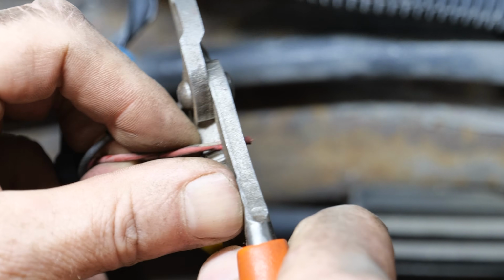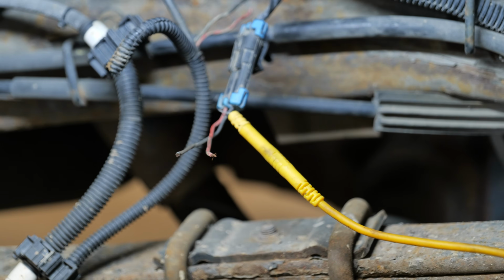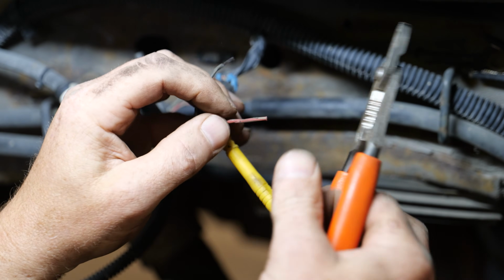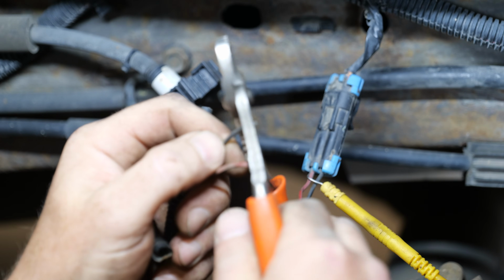The wires are all black and corroded. This really needs this sub harness replaced. Look how nasty these wires are. I'm going to tell Pete to get a sub harness for this, but for this video, we're just going to fix it. That's bad. This harness is just deteriorated. The ground sides are completely black. Yeah, this has been exposed for a long time.